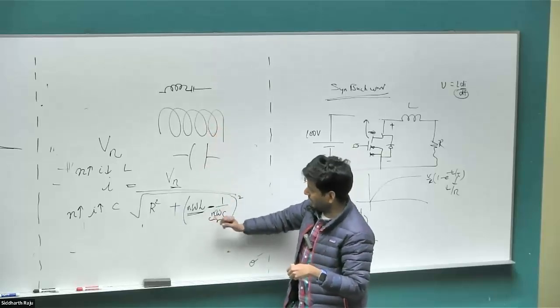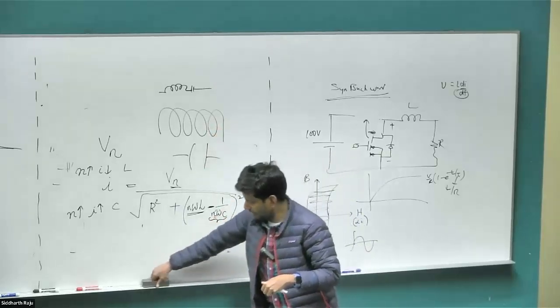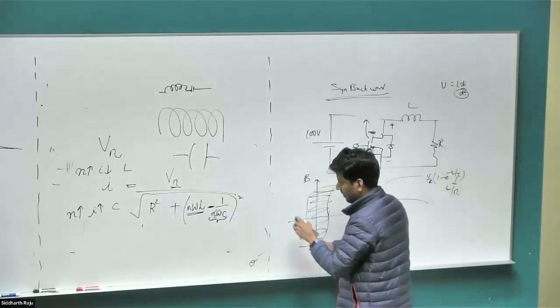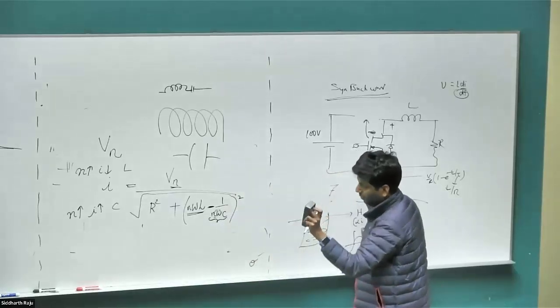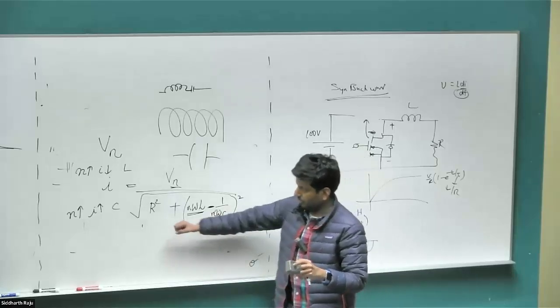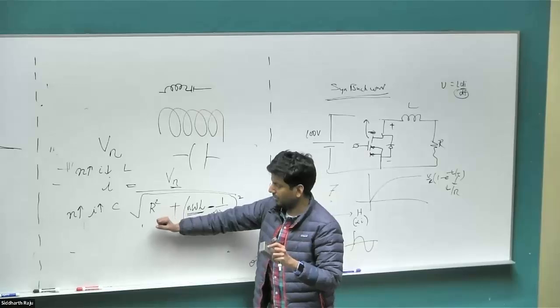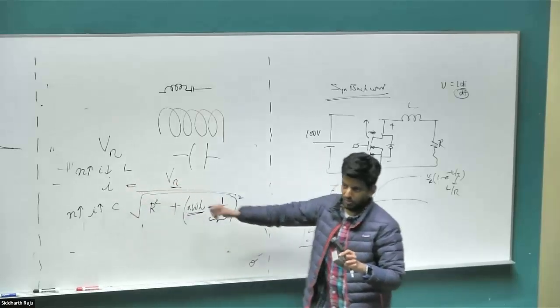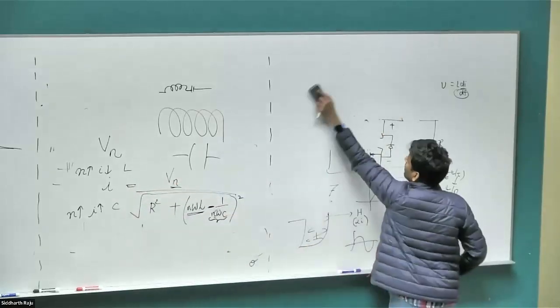So whenever you have an inductor capacitor combination, this would end up being your effective impedance, right? And if you get to a point where the frequency matches the resonance, then this whole term vanishes. It's purely resistive, which will typically be very low in circuits, and then you get a very large current in your network, which will burn out the network.